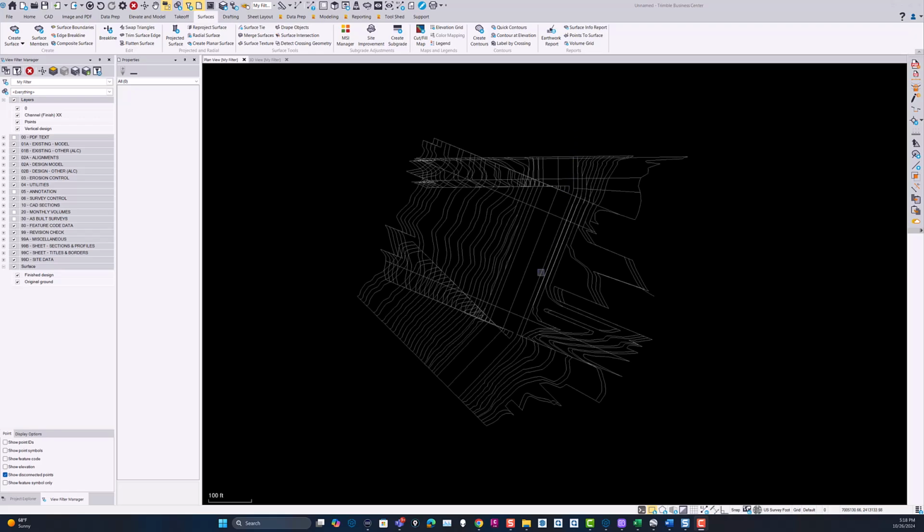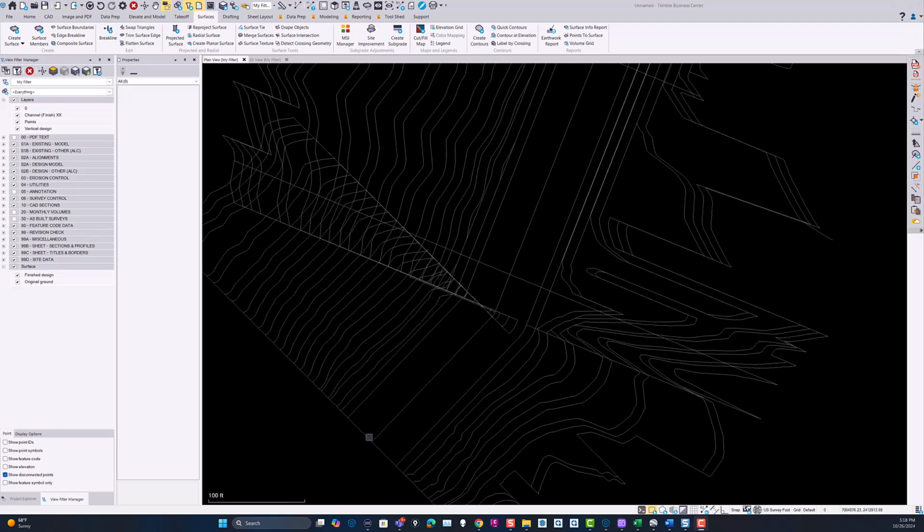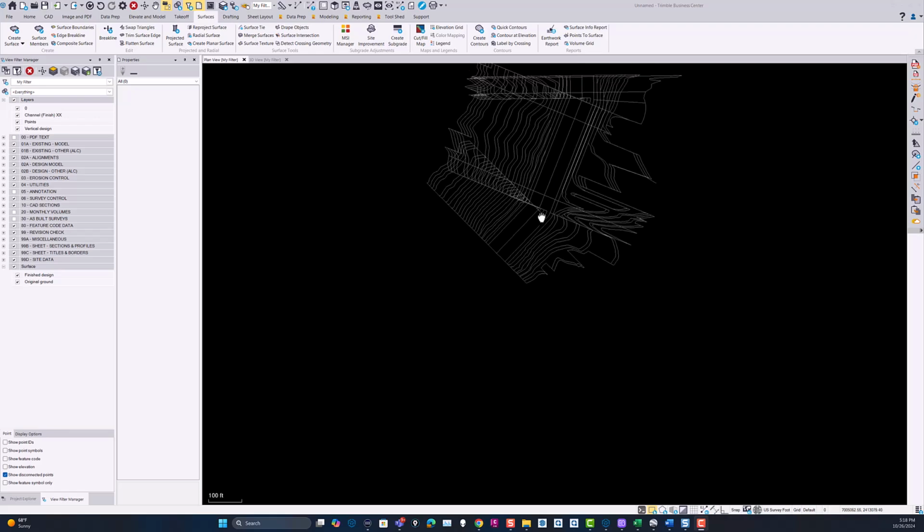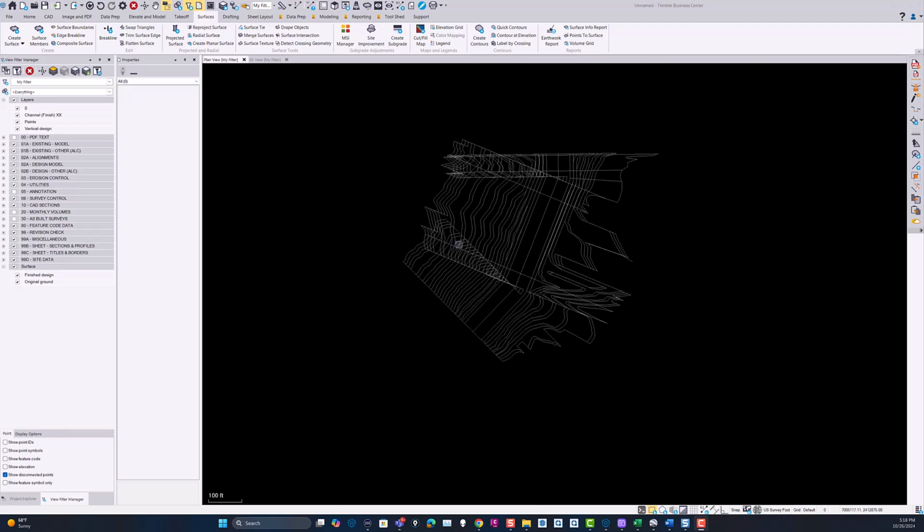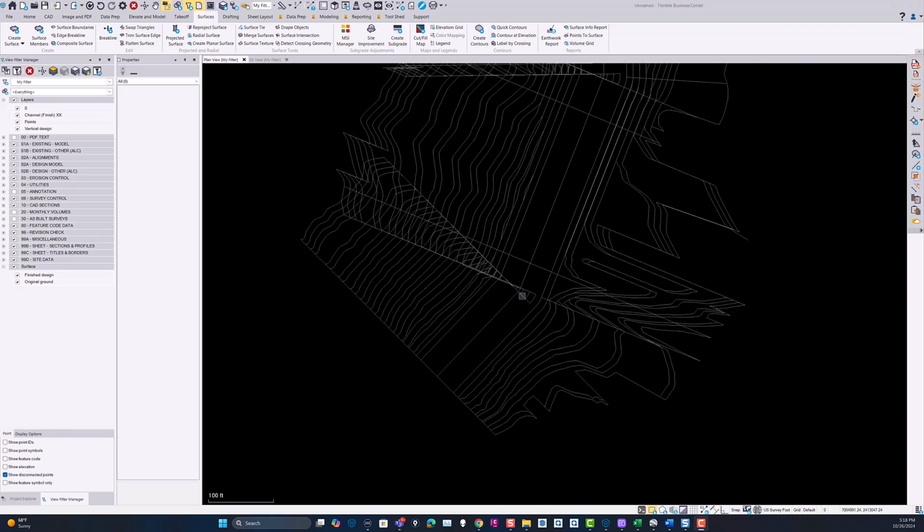Now the corridor model always suffers when these lines are angular lines. When you have an angle corner, when you look on the inside of the corner, you get these overlaps, because from this segment they project perpendicular this way, and then from this segment they project perpendicular this way. So on the internal corner you get these overlaps.